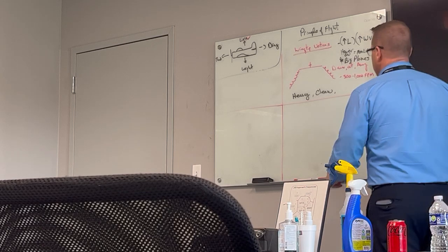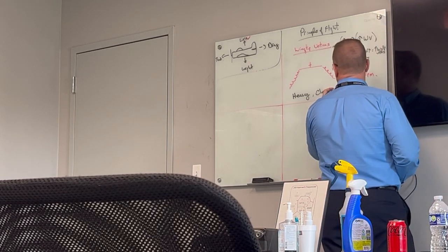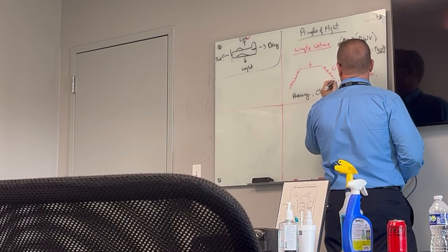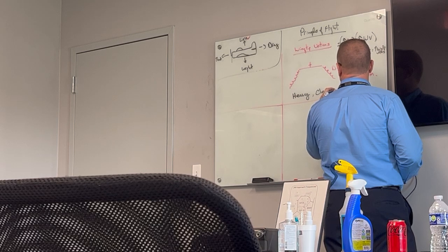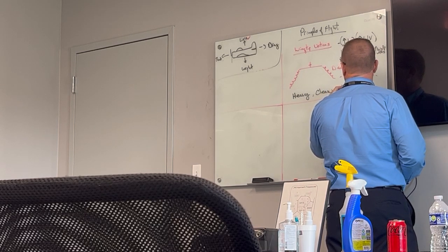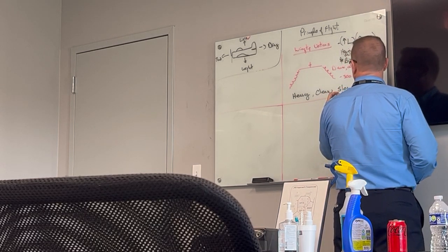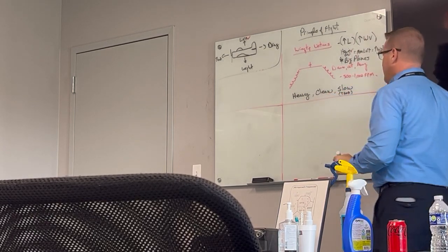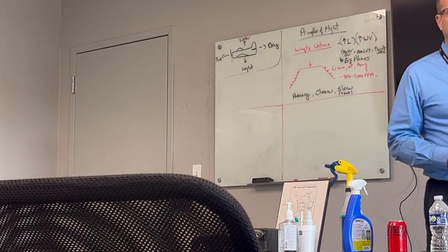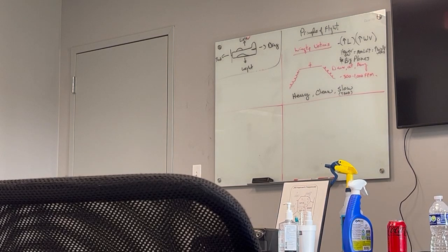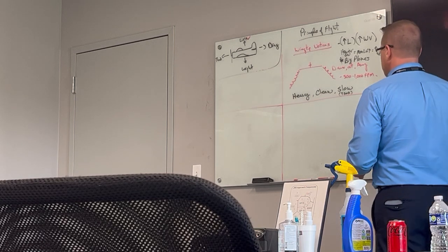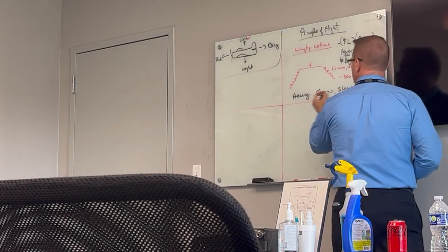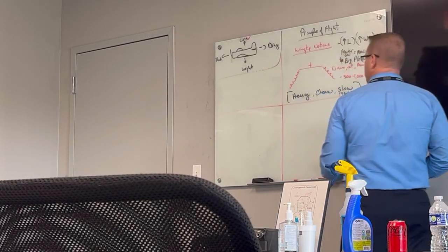And since we're creating the max amount of lift, typically that means we're at a high angle of attack. And if we're at a high angle of attack, we're flying slow, right? So heavy, clean, and slow is the condition in which we want to be worried about the most.